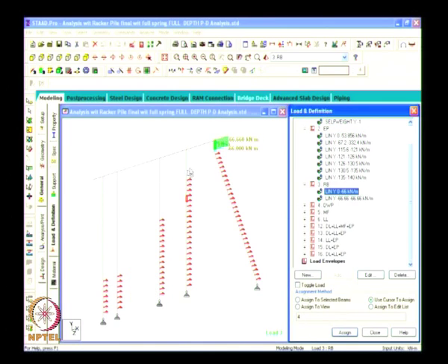Then we have removed the soil above this level. I will tell you why we have removed the soil above this level. We removed above this level to reduce the earth pressure on the main wall. So that earth pressure will go on the back side. This is the earth pressure due to the soil as well as due to the surcharge load.